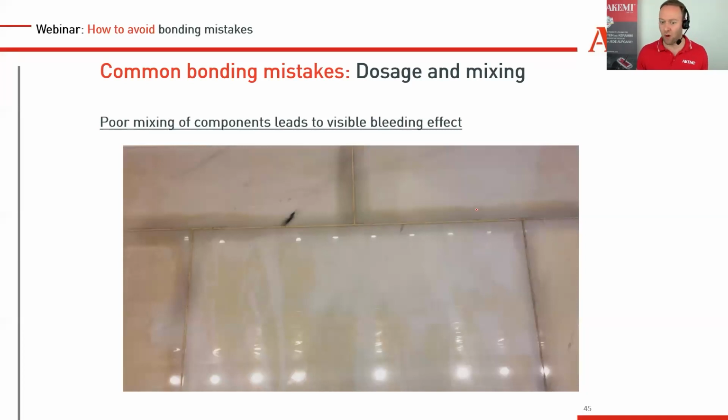They did not mix it right, and all the remaining monomers or polymers, maybe the excess of A component or excess of B component, you never know what they mixed wrong, stays and moves into the stone, into the capillaries, and it will discolor it. And this stays like that. There's no way of cleaning it.